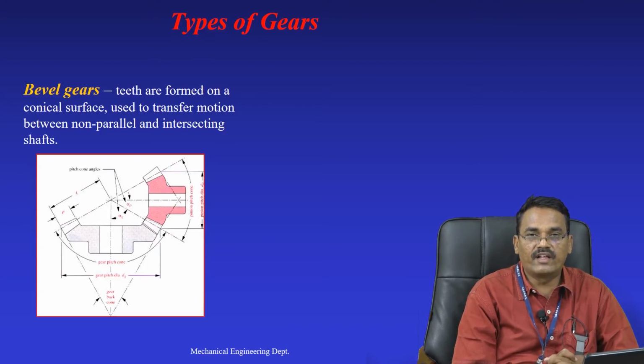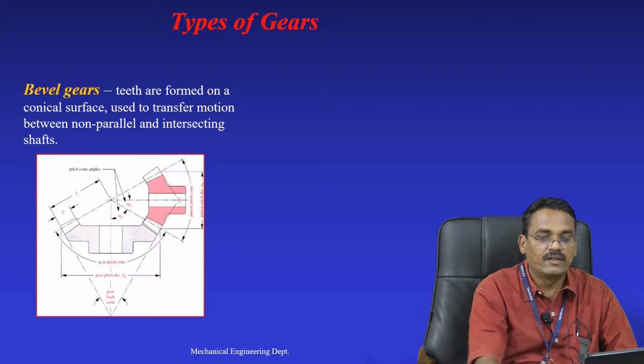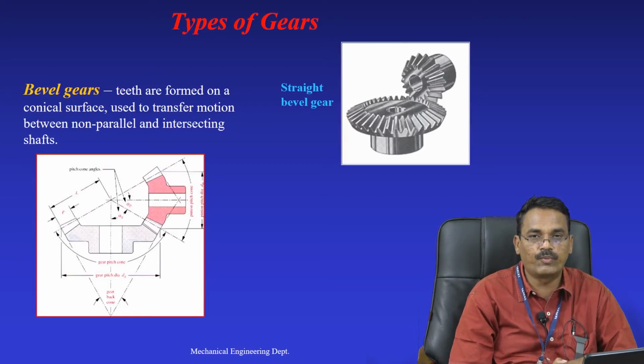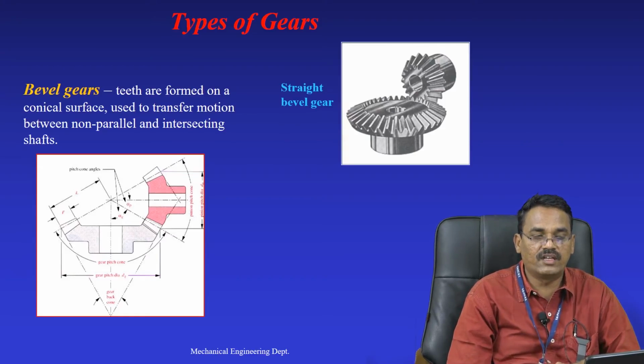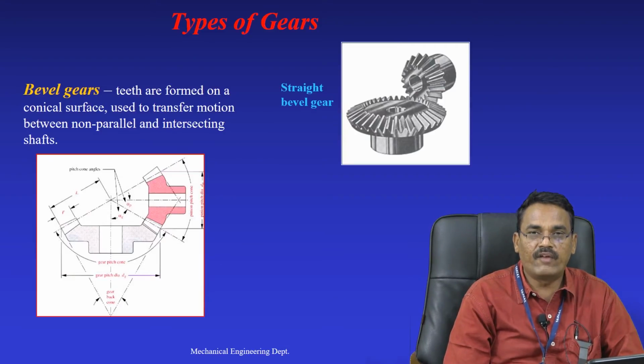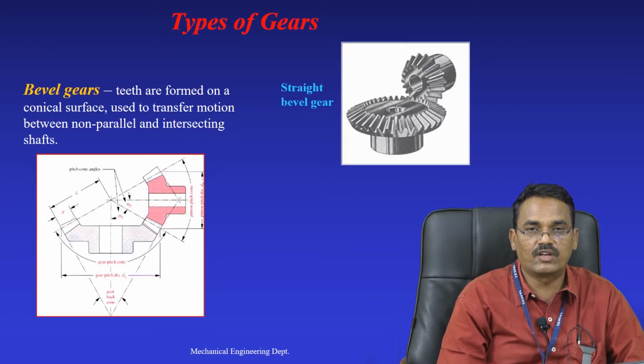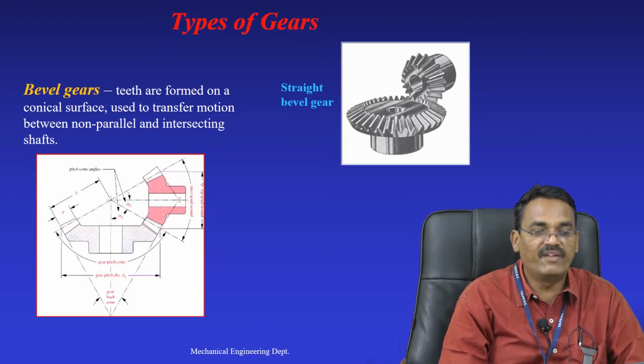In the same way, this figure we call the bevel gear. Why do we call it a bevel gear? In this figure it is clearly seen that the axis of the input gear, called the pinion, and the axis of the output gear, called simply the gear, are intersecting. If they are intersecting, they may have a 90-degree angle, or they may have an angle less or greater than 90 degrees, and such a classification of gear is called the bevel gear.